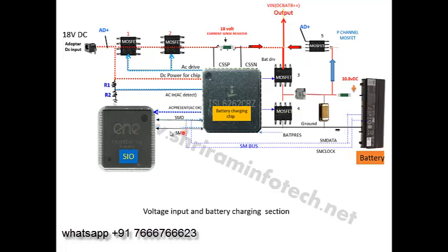Now the next is it communicates with the battery and checks whether the battery needs current. Okay, and if the battery needs current, it develops the current at this battery terminal. The battery has 5-6 terminals, like one positive, one negative, and two for the sensors, one for battery present and another for battery temperature. So like that.